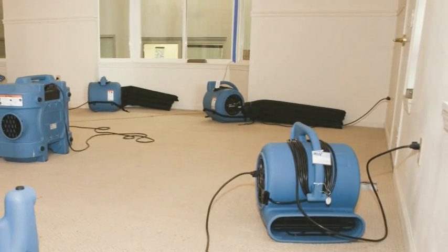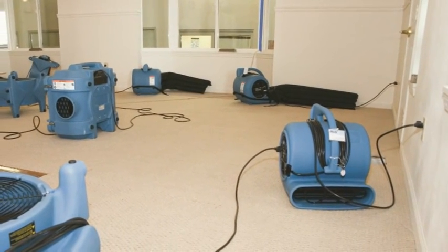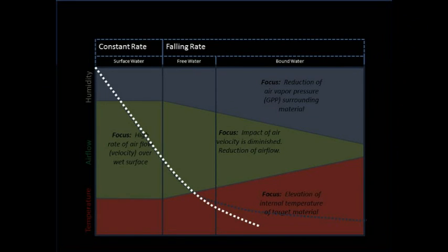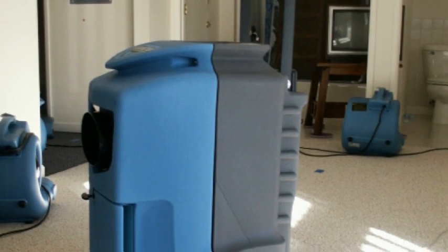If the appropriate adjustments are not made through the drying process, this slope will be very representative of most building materials. Here, we can see that the drying slope is much steeper during the falling drying rate, resulting in a much faster overall drying time. This is the impact of properly managing the reduction of air movement while focusing on a lower humidity within the structure, and as appropriate, ensuring an appropriate amount of energy has been applied to the target building material.